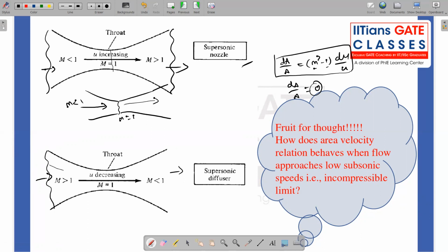So it has to decelerate through a converging duct, because for a supersonic flow, the converging duct makes the flow decelerate. Then somewhere in the throat it becomes sonic, and then again it has to decelerate to subsonic. For that, I have to give a diverging duct, because in the subsonic regime I want a diverging duct to make the flow decelerate. It's very interesting flow physics, through which we are seeing a number of